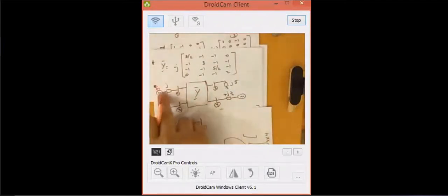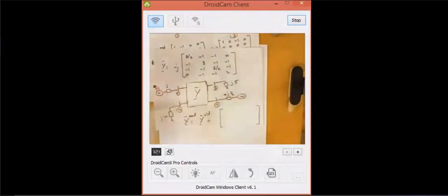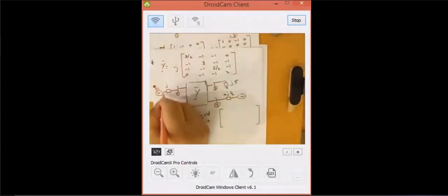So here the voltage source is the same as a short circuit, and the current source is the same as an open circuit. Then we have only the shunt, connected to the ground here, but we need to change it to admittance, so it is equal to minus j. This is connected to bus number 1, so it is going to affect only bus number 1. So it is minus j.